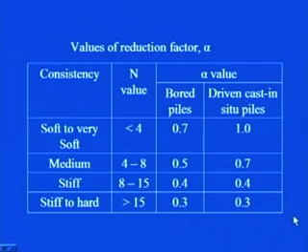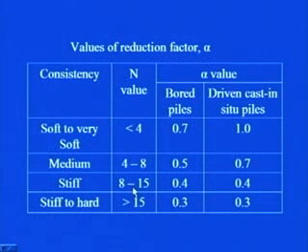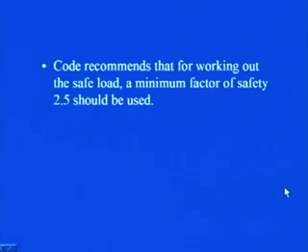So, this just gives you a rough idea. So, here you see if you have standard penetration test data, from that you can simply pick what exactly is the consistency of the clay and accordingly you can pick the value of alpha for bored piles or for driven piles as the case may be.